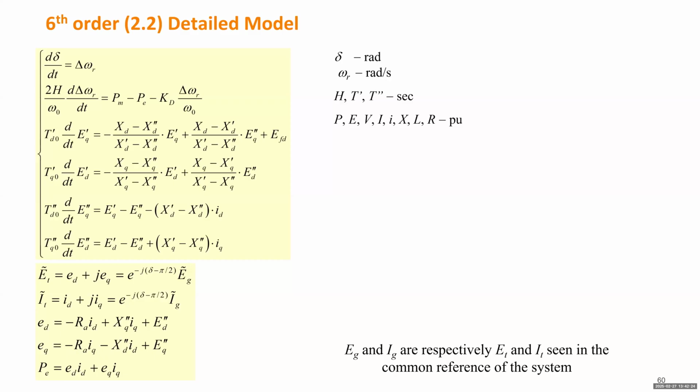Okay, so which means the P is not constant. P depends on both current and voltage at terminal. And those two equations are basically just the first two voltage equations with a subtransient dynamic. Those two equations are new equations added. But if you take a look at the equation, it doesn't do anything. The left-hand side is just the definition of the terminal voltage and current as phasor. And the right-hand side just tells that phasor can be represented by another phasor.